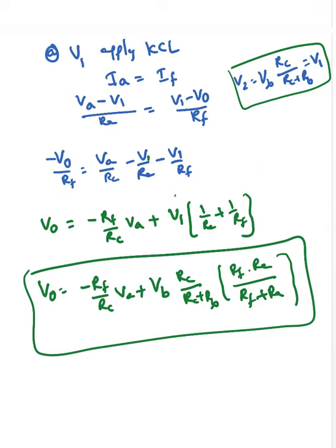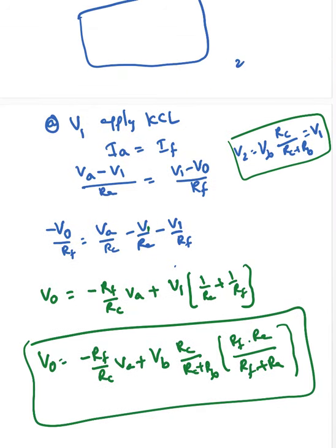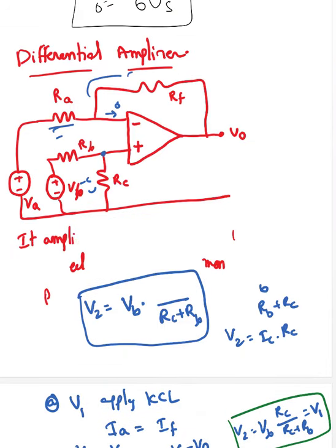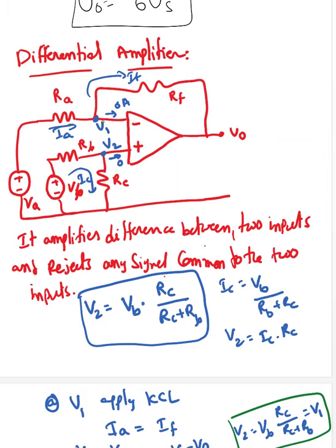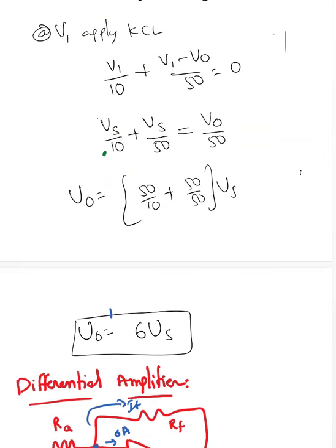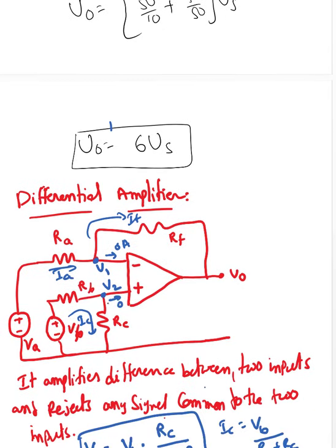So in this video we saw the summing amplifier and the differential amplifier. Now you don't need to remember all these things. The two important things you need to remember are: V1 is always equal to V2, and there is no current getting inside the amplifier. And apply KVL or KCL at V1 or V2 based on the requirement. We'll solve some examples in the next video.